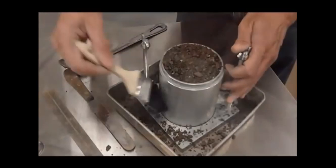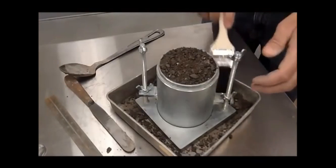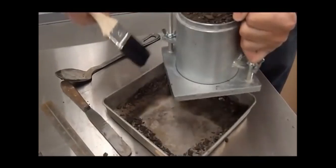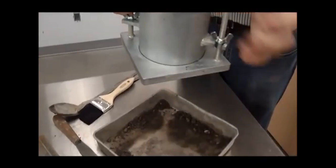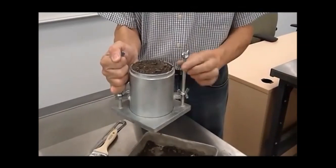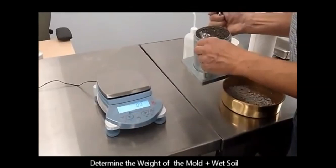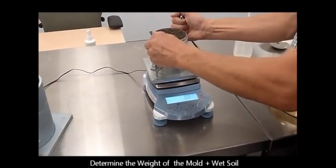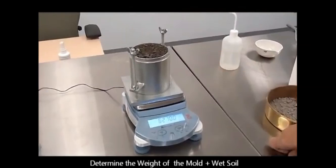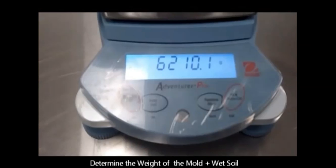Next, I'll clean my mold and the base plate. And I will take the weight. Earlier, I had taken the weight of the empty mold with base plate. Now I'm taking the weight of the mold with soil. Now it is 6,200 grams.